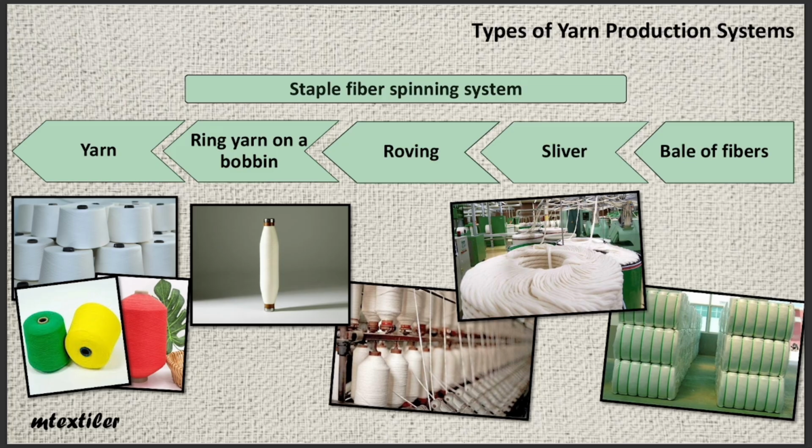Weak and soft points along the yarn that can cause rupture in weaving are also removed. Several meters of yarn wound around ring frame bobbin are joined together in the autoconer to form a yarn bobbin. We can dye the yarn bobbin itself, or, if we have colored fibers from the very beginning, produce colored yarn directly. For cotton and other natural fibers, the easier method and the one that ensures more uniform dyeing is dyeing the yarn bobbin, or the final fabric product.